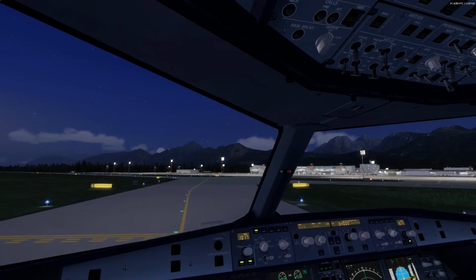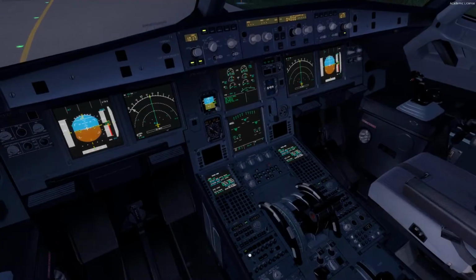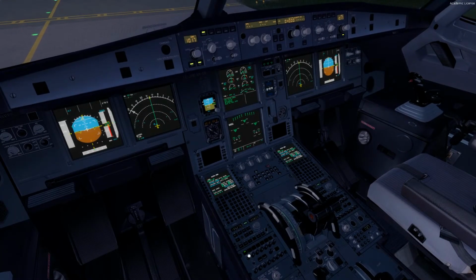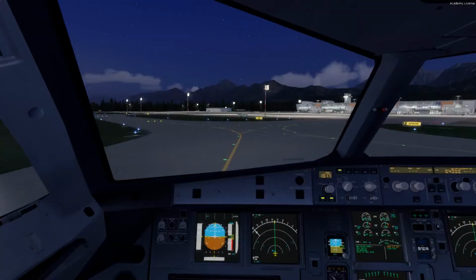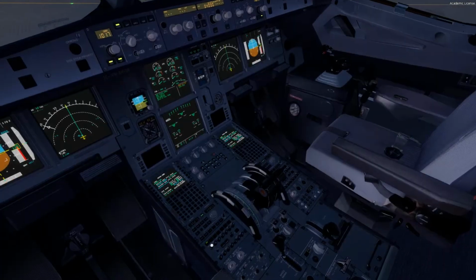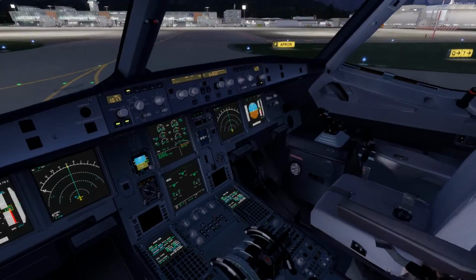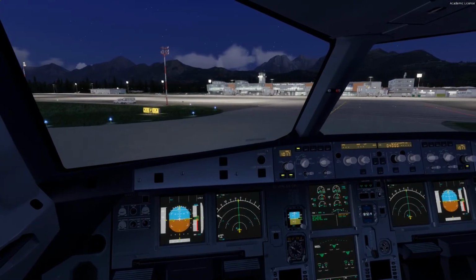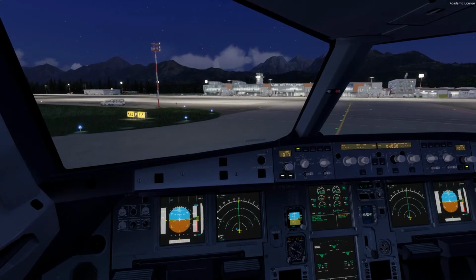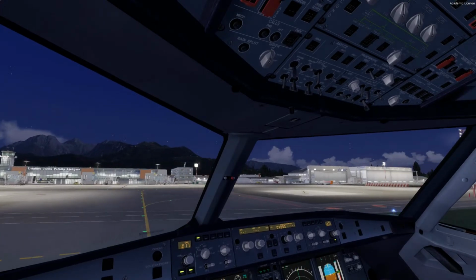The external lights are now off. We just have the taxi lights, and I'll also turn off the transponder for now. And the weather radar, and also proximity warning system. And then the spoilers can be disarmed, and the flaps are set to position 0. And now we'll taxi to position number 3, which has a jet bridge right there. And we'll also start the APU.